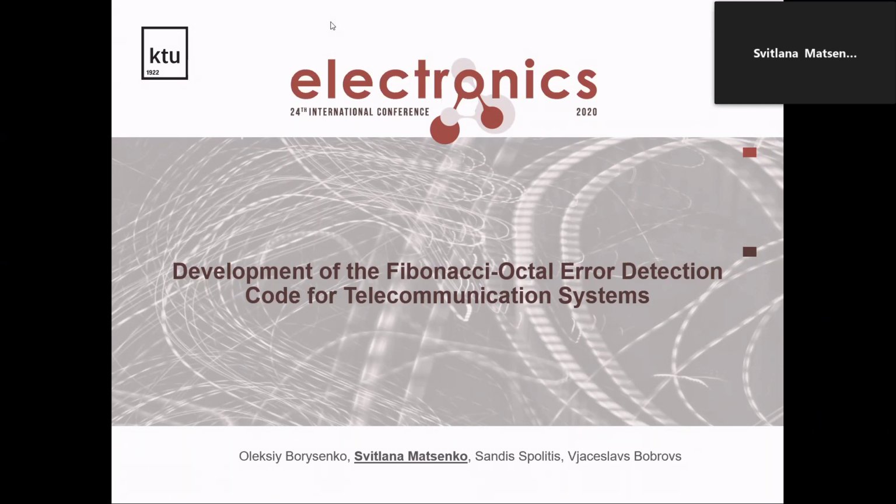An important task necessary for a telecommunication system using the Fibonacci code is the ability to convert it to binary code for communication with binary digital systems, and vice versa, to convert binary codes to the Fibonacci code. To convert data, we propose to use the Fibonacci octal code, which consists of a sequence of 4-bit modules containing 8 Fibonacci numbers.